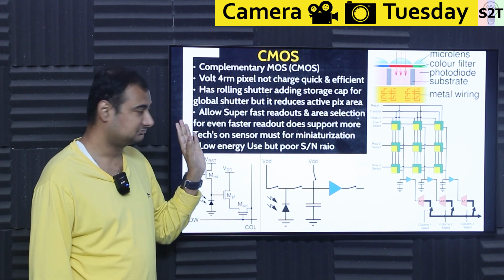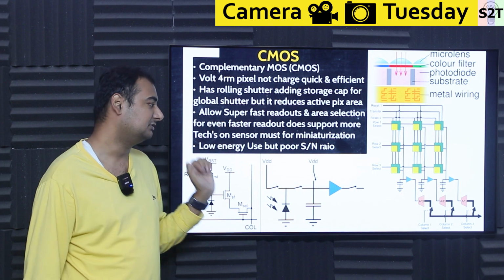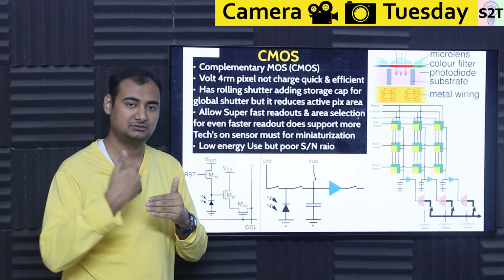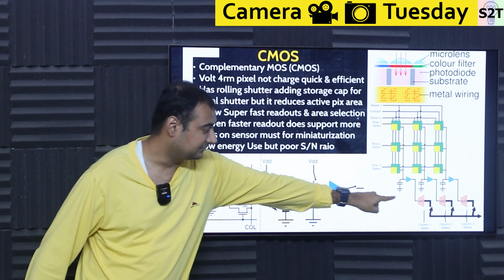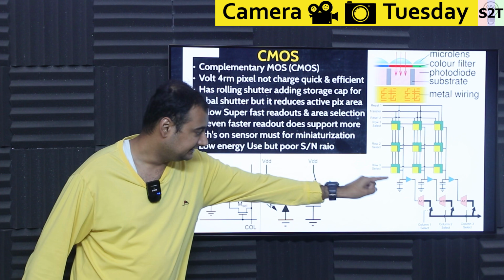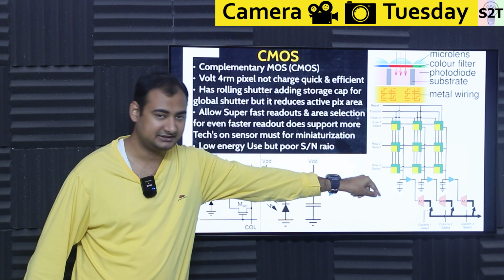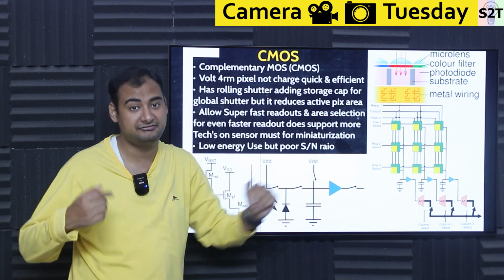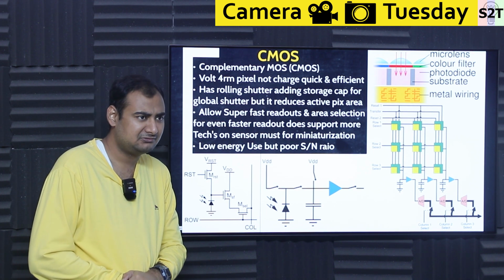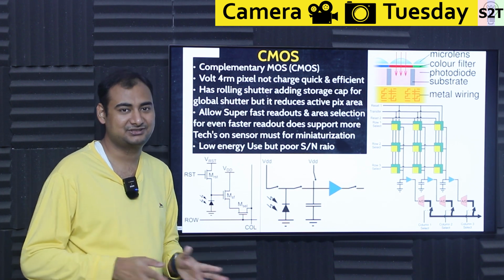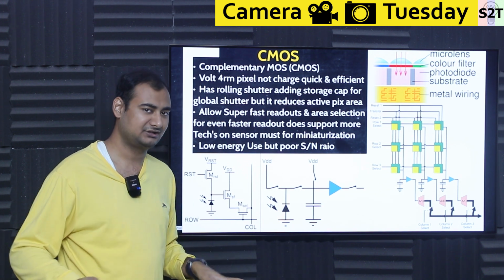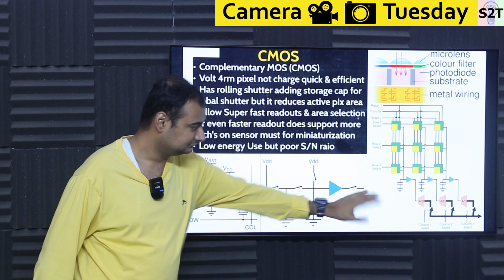On top of that, because of the technology of CMOS, it allows what we call on-sensor technology add-ons, meaning multiple sub read arrays. That's why multiple analog to digital converters, so it can read much faster. Stacked sensor, it has the analog to digital converter right there, so the voltage signal gets converted very quickly. It improves your readout to such a point where it's like, do you really need global shutter? Actually, you do need it, because it removes all the issues. This is close. Global shutter is like, don't ask about it. So that's what we can do.